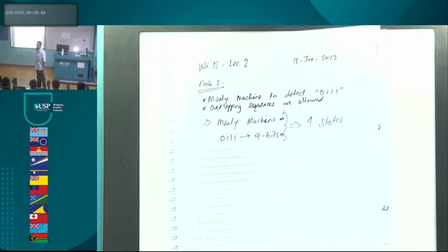Now, what is the good news about 4 states? If you were to do 4 states, how many flip-flops do you need? You need 2, because each flip-flop is 1 bit. In order to achieve 4 states, it's 2 to the power of 2, which is 4. Now, this is the game changer. If this was a Moore machine, how many states will we need? It's always Mealy plus 1. So Moore will always be 5.